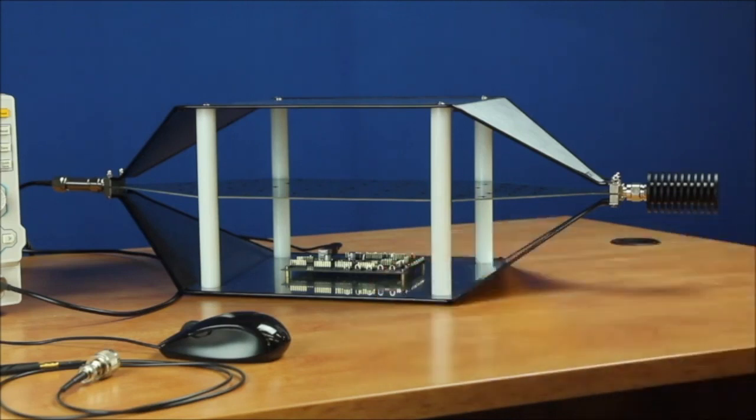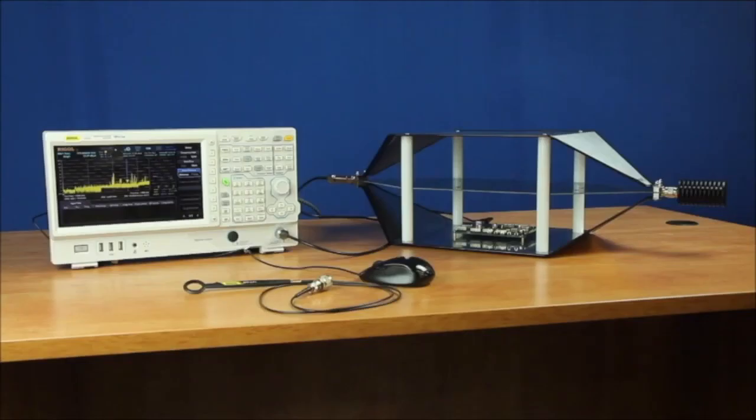In an open TEM cell of this size, the general rule of thumb would be emissions above about 40 dB microvolts are really areas of interest or concern for our ongoing testing. So we can do this setup in any kind of a room with our spectrum analyzer where we can start to see emissions in a radiated sense to validate.